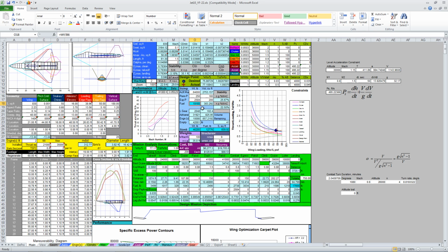And the way we do that is we take our input aircraft takeoff gross weight, subtract the weight of the landing gear, the airframe, the engines, and the expendable and permanent payload. And whatever's left must be fuel. And as long as there's room to fit the fuel in, and there's 41 cubic feet of volume remaining according to our estimates. So, what do we do with all that extra fuel?